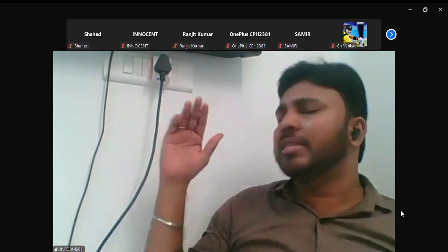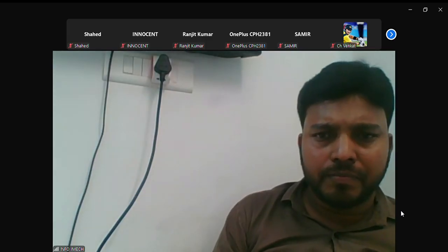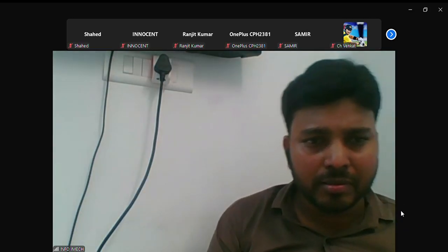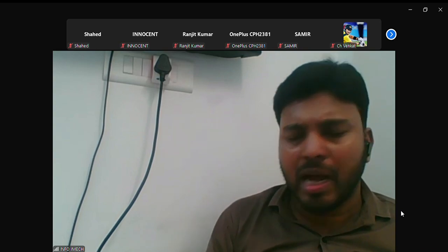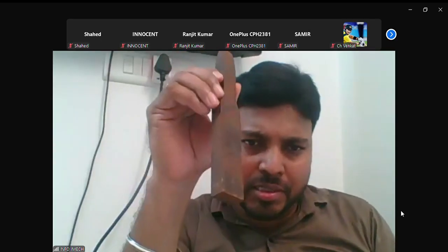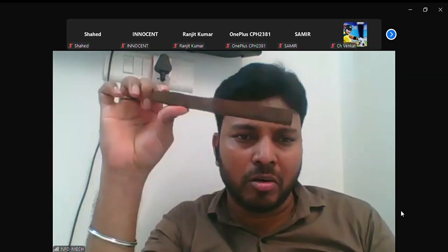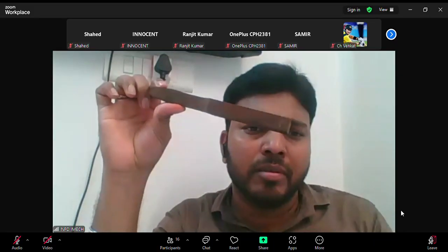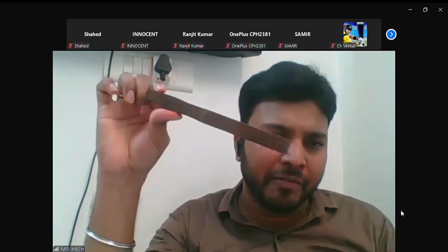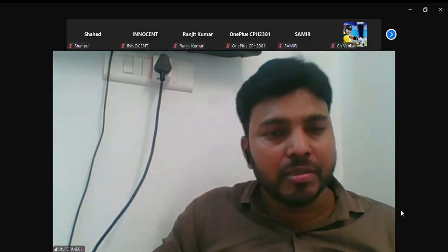For example, I want to test this wall for thickness or any internal defect, at what depth the defect is, at which location. Or else this metal the customer provided: I want to know whether it has any defect inside, and if so, at which location and at what depth. UT can give that information.